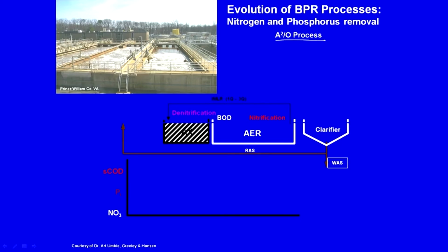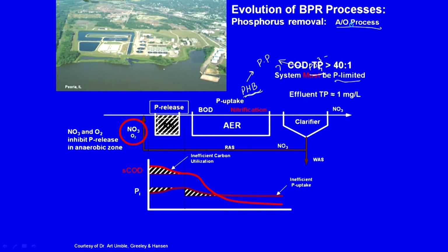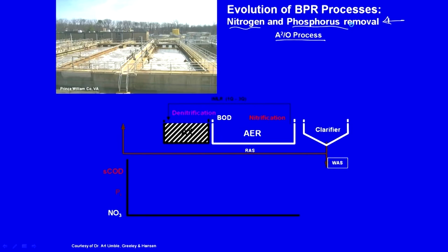Here also you have the aeration basin, before that you have the AX is, I guess, for anoxic. So, this will in a way remove nitrogen, that is something we looked at. That is why I wanted to look at nitrogen removal also earlier. So, we are now looking at nitrogen and phosphorus removal, right. Earlier it was primarily phosphorus removal, here we are looking at nitrogen and phosphorus removal. So, it is the A2O process.